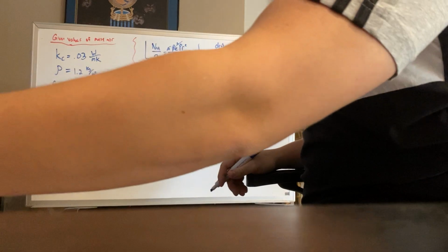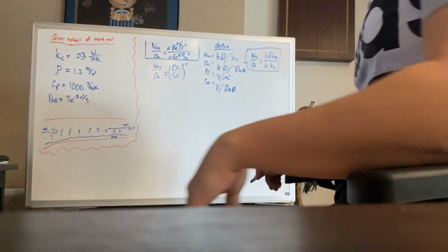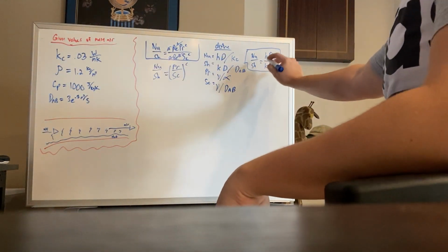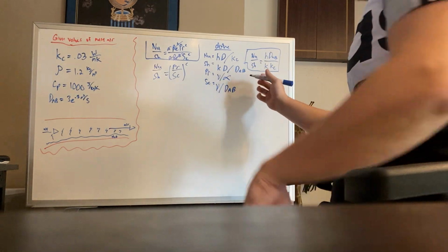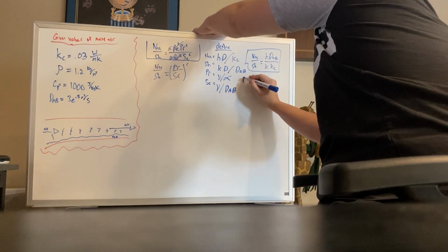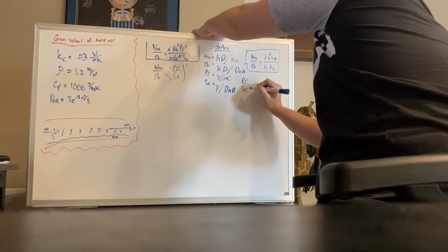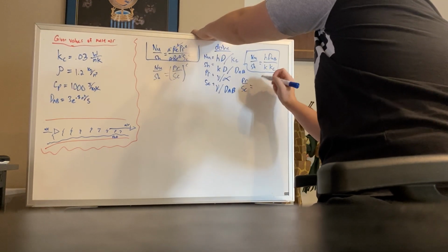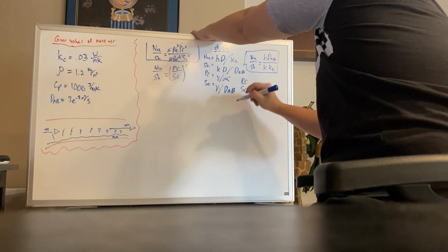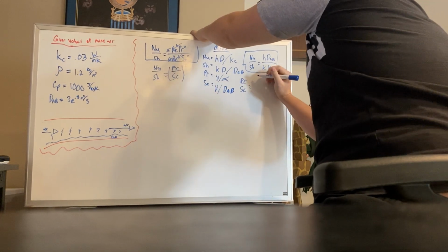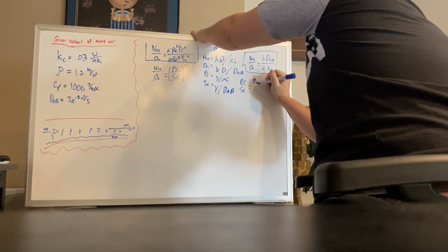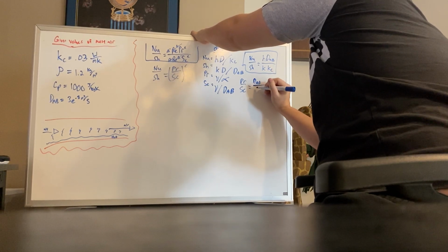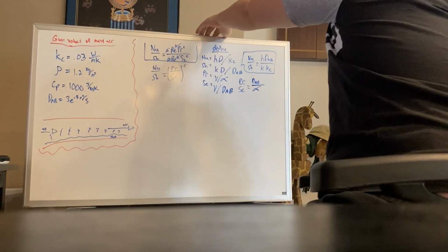So now that we have these, we can also combine these two in the same way that we did before, where we will have the Prandtl over the Schmidt like we have in the problem that we condensed to. The kinematic viscosities will cancel out. So we'll keep this, change this, flip that, and multiply it. So we are left with the diffusivity constant from A to B all over alpha, the thermal diffusivity.